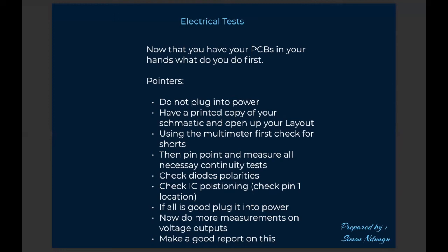Are the ICs legit ICs? Because we've had issues where some Chinese fab houses mounted components that are not working, and it's an IC, something you cannot suspect in your design. You end up scratching your head too long looking into your design. You can't find any bug, only to realize that you had a bad IC. So perform these electrical tests before plugging your device into power so that it may not blow up, because you don't know how the design is until you first do some electrical tests. Very critical.